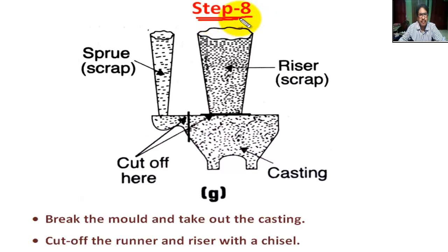Next, step 8. This is the final casting. In step 8, break the mold and take out the casting.